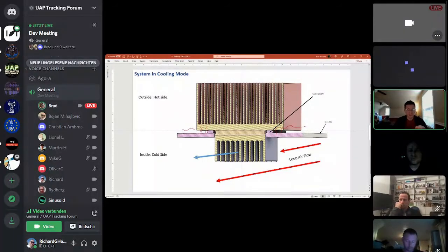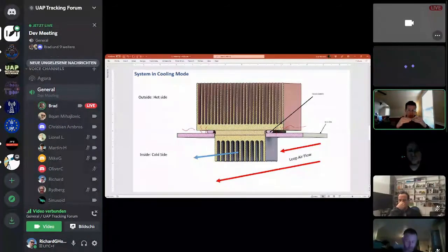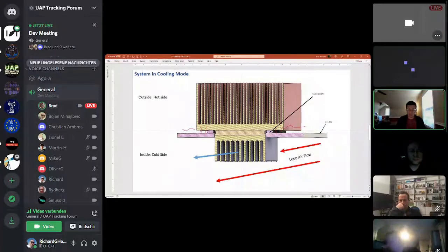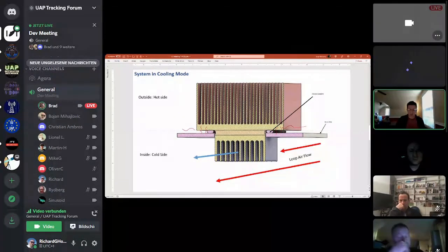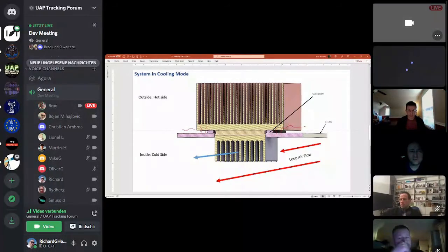It doesn't spread easily, and if you get it too thick, you're going to limit your heat conduction. Yep. So every layer you're adding on top of that peltier plate, either the hot side or the cold side, for spacing, you're going to lose in terms of efficiency. And remember, we've got someone who's going to be like me and makes a mess of thermal paste and glue, screwing this up completely because our users are going to have to build this on their own. So every layer we add adds the likelihood that it's going to get screwed up and perform suboptimally. So if we could avoid using spacers in the design, that would be fantastic.